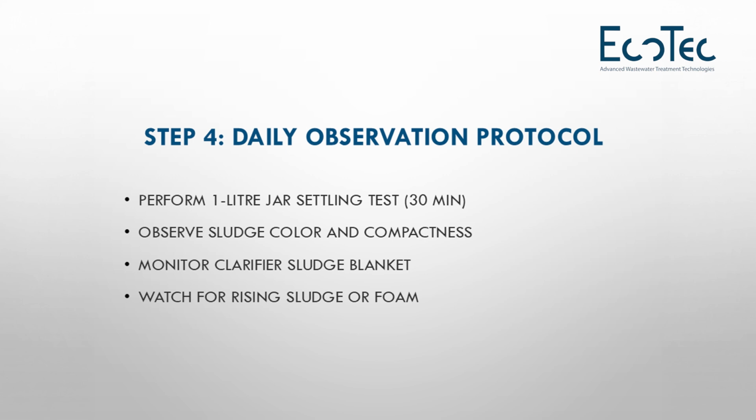In MBBR, observe media movement, excessive biofilm falling out, color of the mixed liquor. Before analyzers existed, plants operated successfully. Today, with all the sensors, what we have is sensor failures, and many plants collapse. This is not automation failure. This is dependence without basic understanding of sewage treatment systems.